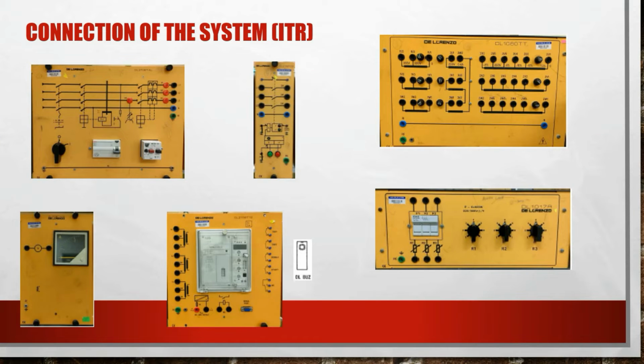After that, the connection of the system ITR. For ITR activity, we need many components like three-phase supply, circuit breaker, the transformer, the ammeter, the relay, the load, and the buzzer. So connection of this equipment is first connect the L1, L2, L3 and neutral to the circuit breaker, and then this is the connection from circuit breaker to transformer.